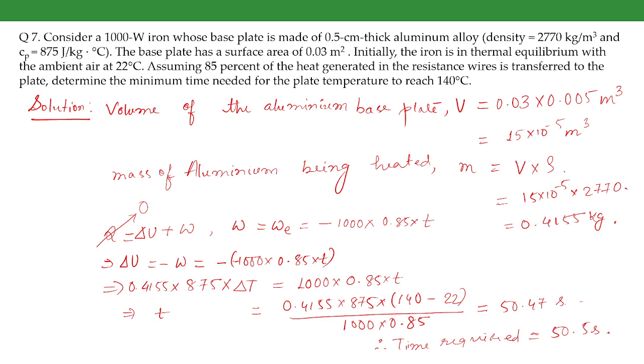So there is no forced convection, and the natural convection heat transfer coefficient, if you take, it will be around 5 watt, or even in that range. And this is convection, so it is only by natural convection. And the rest part is radiation. Radiation becomes significant only when the temperature is very, very high, because